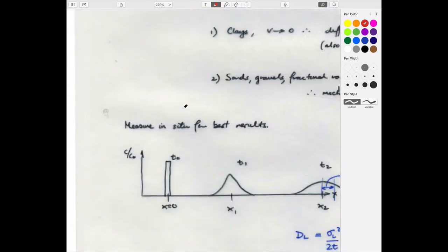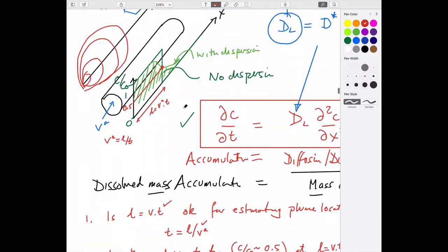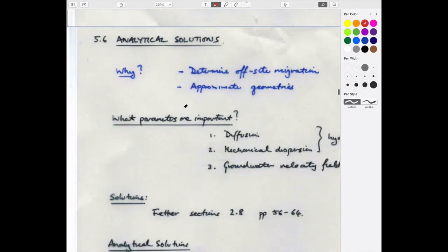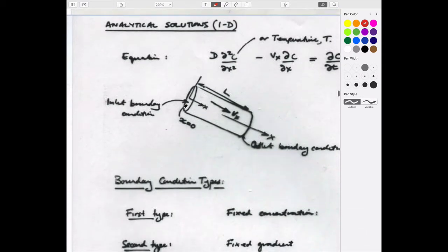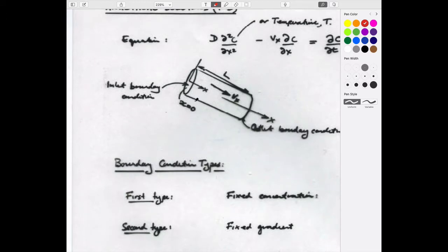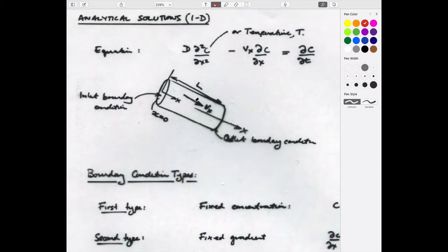where we're looking at flow in a tube that's filled with sand, say, and then we'll take this to look at the case where we have three-dimensional behavior. We need to solve some differential equations. We won't do that, but we'll make note of the fact that the basis of what we're attempting to do is work from this advection-diffusion equation. We can take our tube and look at the flow from the upstream, going at some velocity in the x direction, which I guess is this here, same as the velocity that the water comes out at.